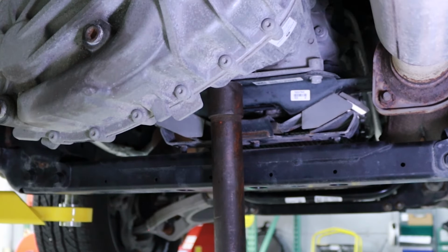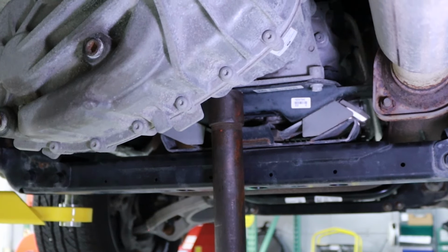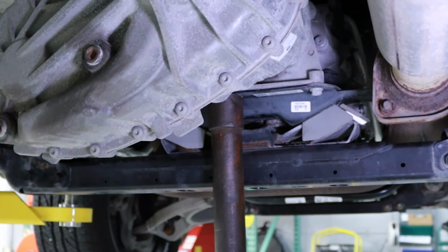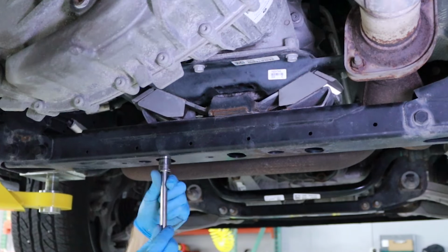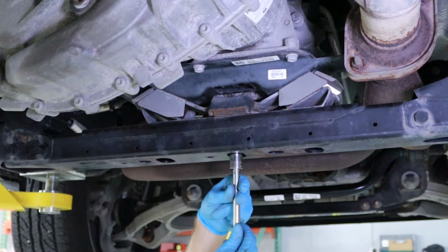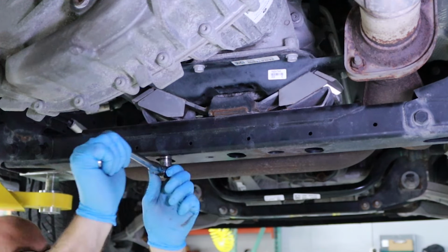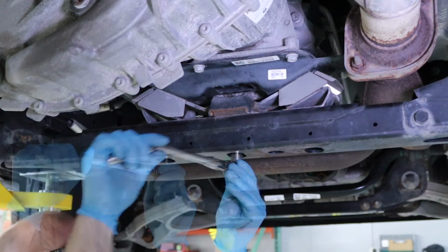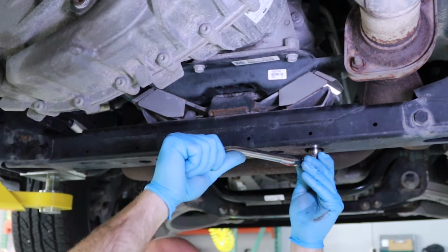Next, if your model had the deeper transmission pan, you can now lower the transmission back down onto the crossmember and remove the underhoist support stand, placing it out of the work area. Next, reinstall the 3 transmission mount nuts, threading them in a clockwise direction. Using a 16mm socket and torque wrench, tighten the nuts. In our case, we ended up tightening them to a 30 foot-pound torque specification.